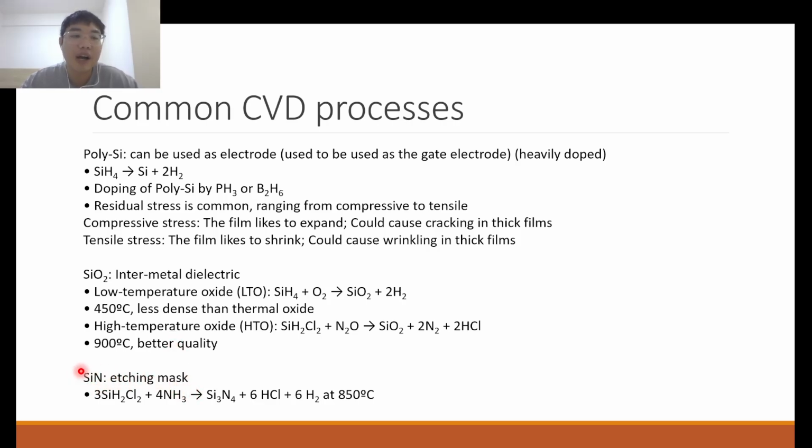Okay. So why I wrote SiN, not the official or proper Si3N4, is because by tuning the stoichiometric ratio of your two gases, you can actually get non-stoichiometric SiNx, where x can be a non-integer value, or not a nice ratio. So we can do that to obtain certain desirable properties of the nitride.